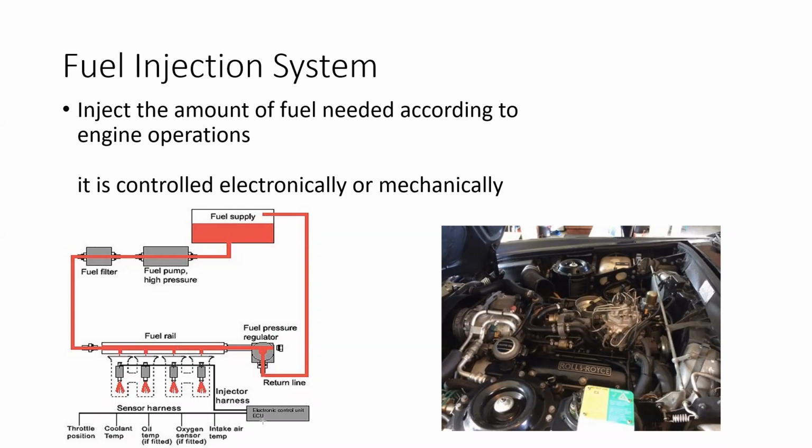So for this fuel injector to operate, the timing and everything depends on, until here, everything is automated, right? Nothing is measured up to here in the basic version of a fuel injection system. It's all mechanical up to the fuel rail and the pressure regulator, everything mechanical. No electronic interference to any of these things, right?